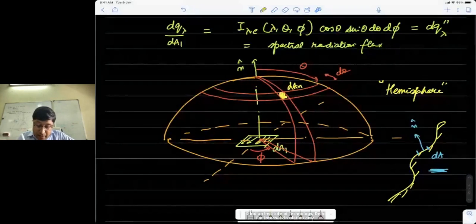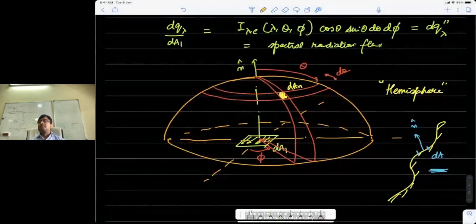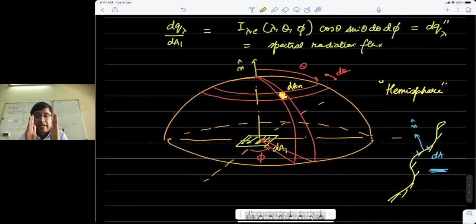Okay, one more thing. Like you said, in the case of a plate which radiates from both above and below, will there be an interference of radiation from the below and above? No, no. Because remember, even a plate which is thin still has some finite thickness, and surface radiation is a phenomenon which happens only within a micron thickness of the surface.